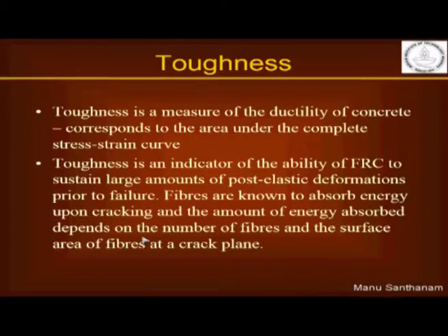Now, as I told you, the importance of the post peak behavior comes into play only when we deal with special concrete such as fiber reinforced concrete. Because fibers have the tendency to prevent the growth and propagation of the cracks, they tend to increase the level of deformation that the concrete undergoes before failure. Okay. So, I am going to give you an example as to how fiber reinforced concrete was able to increase the toughness of your concrete.